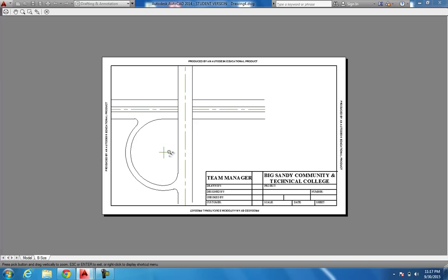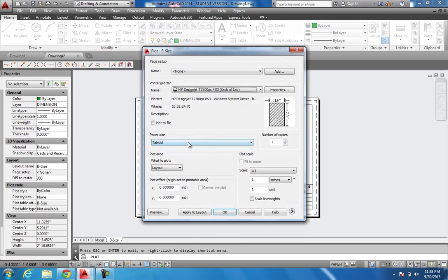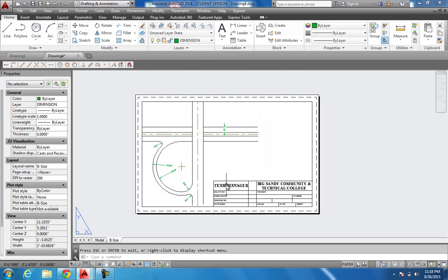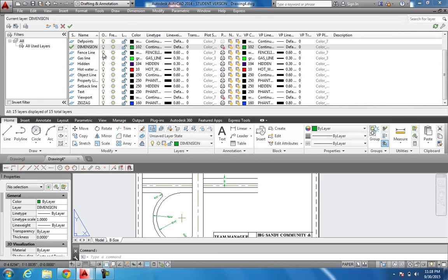And you're starting to wonder, well, there's something missing here. Where'd my dimensions go? Close out. Let's figure out what's going on here. Something's majorly wrong. First thing I would do is come up here and look at your dimensions in your dimension properties. Look across here, check that out. See how the printer's turned off? Just like the viewport's turned off. Click on that and turn it back on. Now let's go take a look at it.